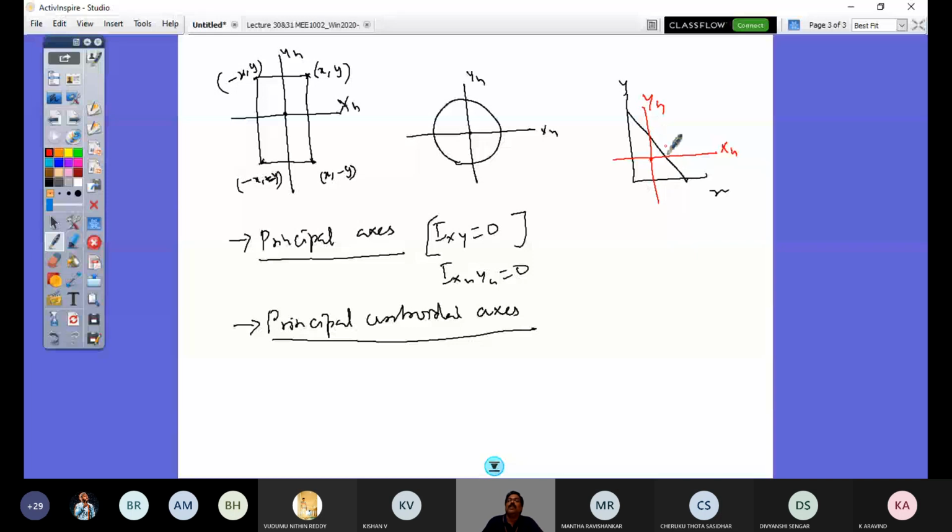Now you see the spread of this area in first quadrant is small, second quadrant is trapezium, this quadrant it is a square, and in this quadrant it is another trapezium. So the areas are uneven. So you would have your product of inertia about XG-YG axis, you would have about XY axis as well, right? So your IXY in this case about the XY axis is going to have some positive value. Whereas your IXG,YG, if you look at the value, what you get would be negative value.